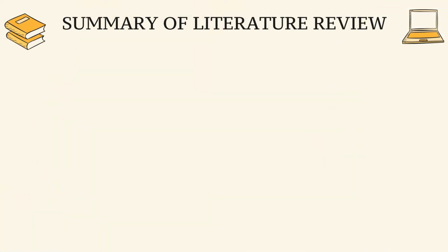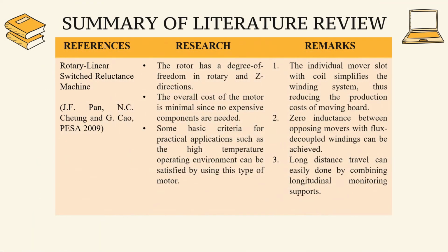The first rotary linear study is about the rotary linear switch reluctance machine. In this research, the rotor has a degree of freedom in rotary and Z directions. The overall cost of the motor is minimal since no expensive components are needed.